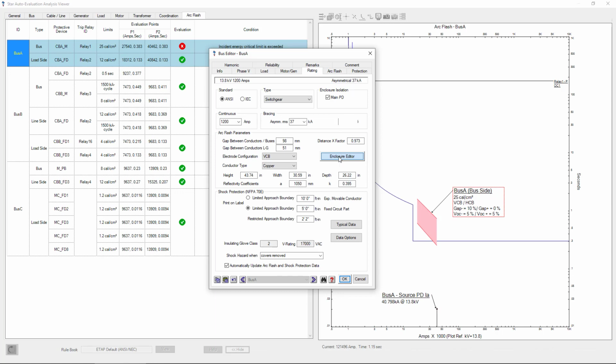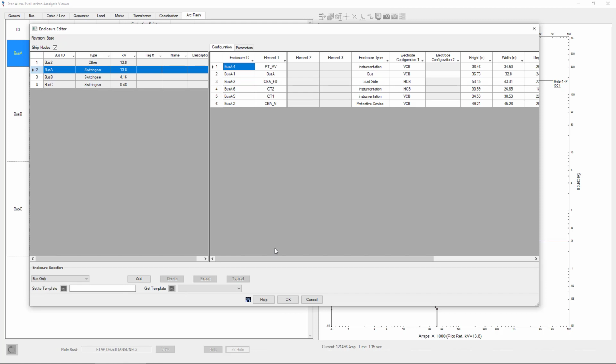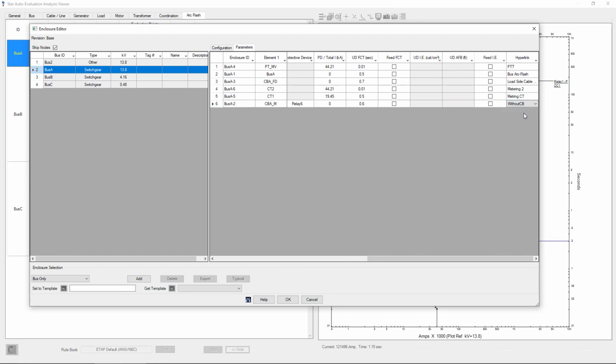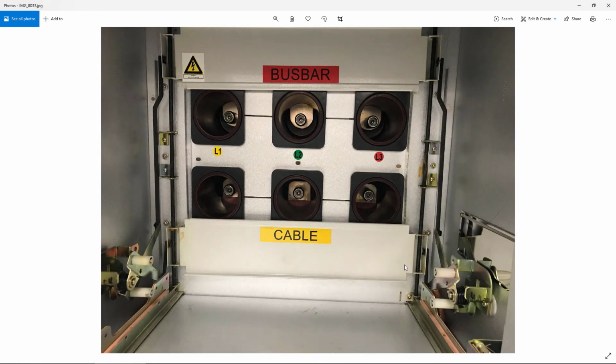If you go back to our graphics for this location, we can go now to the main breaker and observe that this particular enclosure is inside the main circuit breaker, and we do have potentially a horizontal conductor in a box inside the cylinders for the stabs of the circuit breaker. This particular electrode configuration could release a high amount of incident energy, and therefore, unlike the previous example where we were able to dismiss the HCB electrode configuration, in this case we cannot.